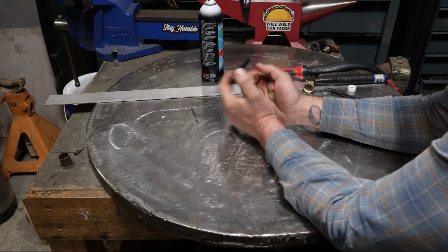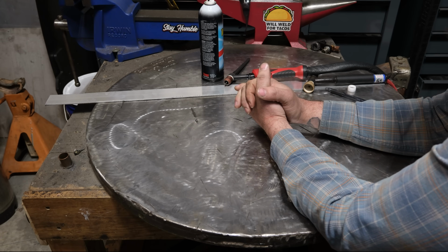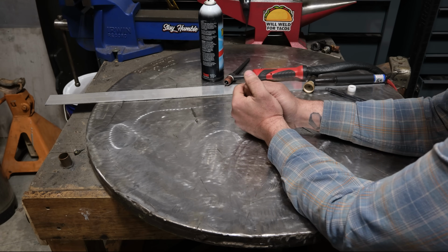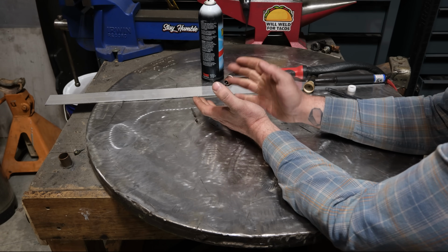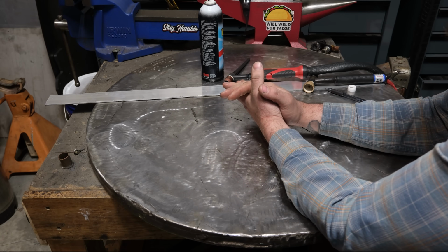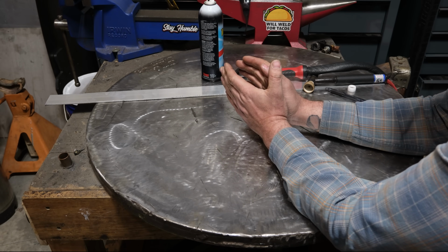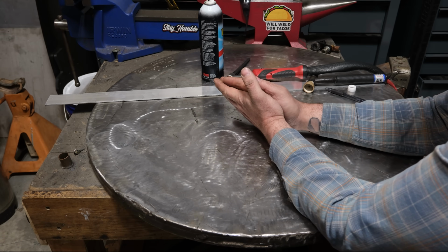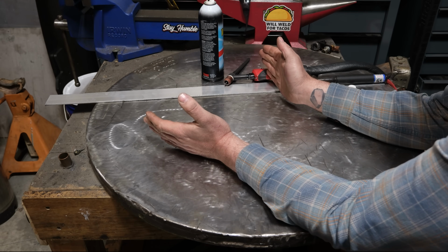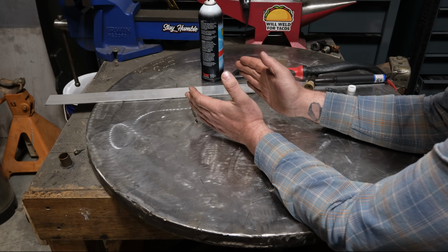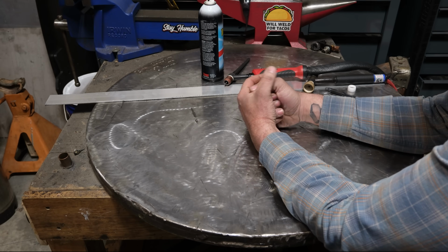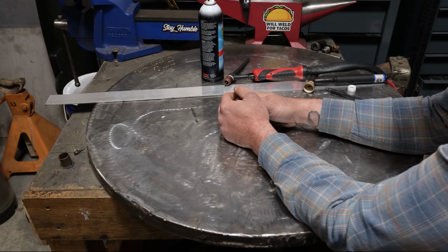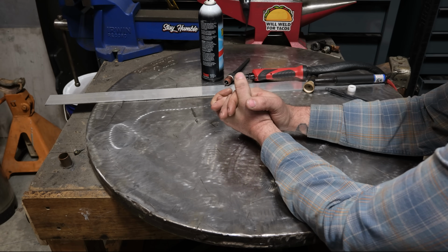I have talked to a ton of people over the years that tell me, I can't get the AC TIG welding to work right. And then I ask them to send me a picture of their welder with the settings or tell me what settings they're running, and everything is all wrong. And once they get things dialed in to where they should be, things start to make sense and work. And that's the key takeaway: you really have a lot of range in settings with aluminum, but at the same time, they have to be in a general area for things to work. And rarely are you going to achieve better results screwing around with settings and putting things at the maximums, or at least that's my opinion, and I'm going to stick to it.